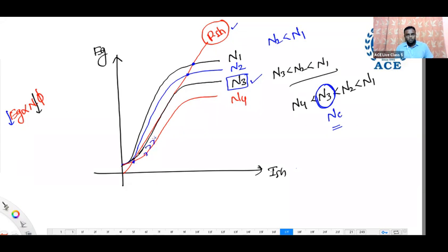Actually, all this will not come. It is just showing; it won't come. This is wrong. Only this will come and stop. Further, there is no voltage buildup. Just for proper sequence, the drawing is continued up to here. Okay. Clear now? Critical speed is the minimum speed we have to rotate. Now, make a note here.